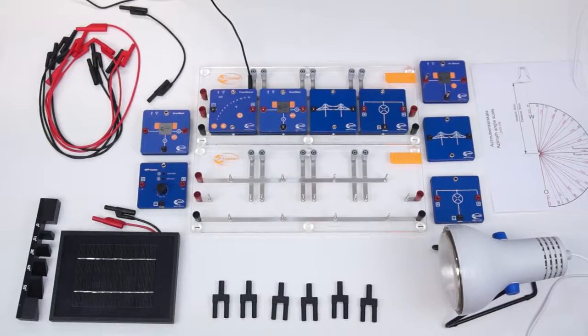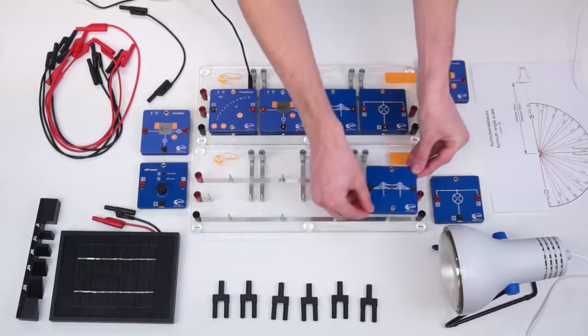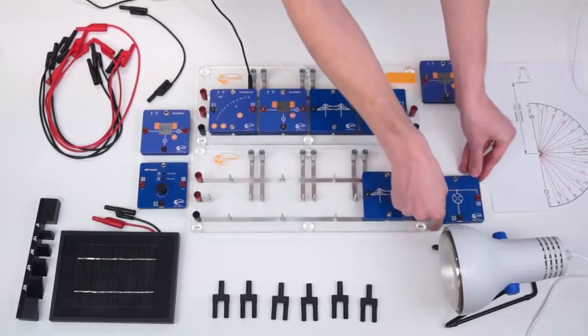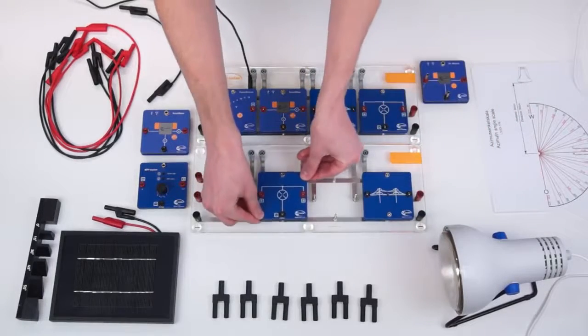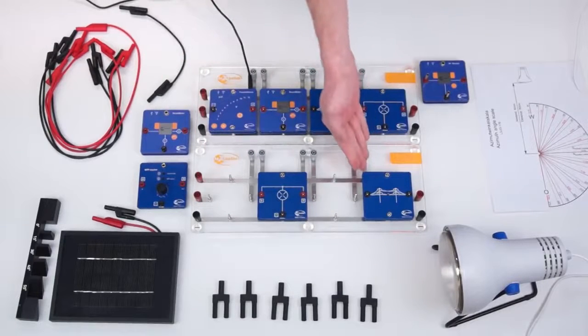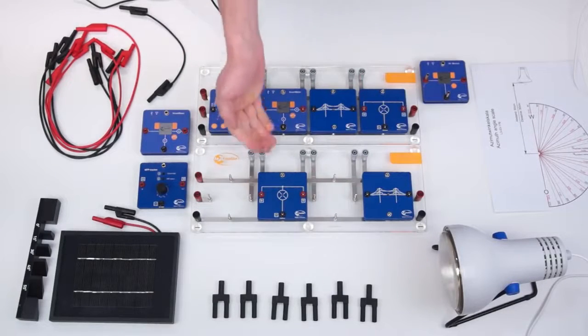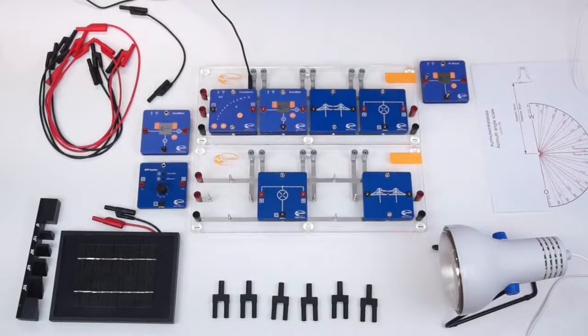For the next section of the low voltage strand, we need the second base unit. It will also be initially equipped with a grid module and a light module. These simulate the line resistance between the 2 houses and the second house. To illustrate the problem of overvoltage, we will install a photovoltaic system with MPP tracker at the second house. Before the house, a power meter is connected in order to investigate when the house absorbs energy from the strand or delivers it.